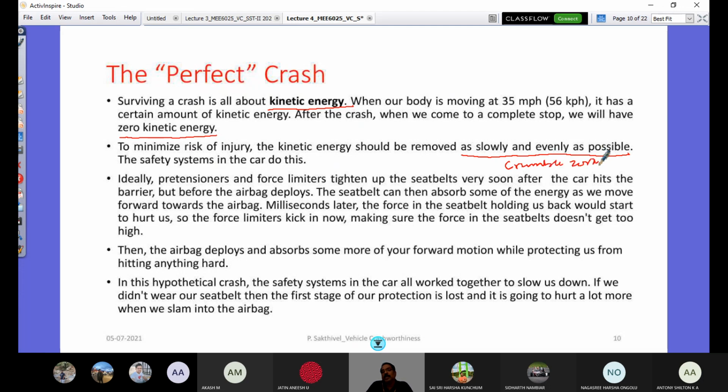So the crumple zone is another passive measure of safety in the structural design of the frontal portion or the rear portion or the side pillar strength and so on, all to bring in the energy to be taken during the collision completely, and there should be zero crash pulse entering the human. There is no energy that goes to an occupant, right? So that's what is called a perfect crash.